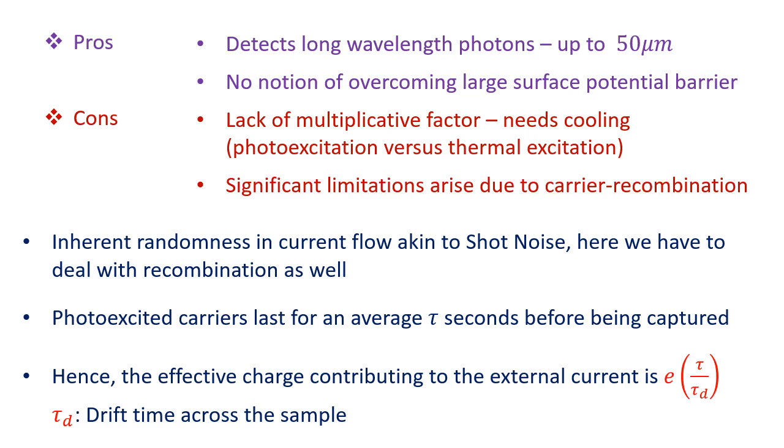Because they are of similar wavelengths and energies. So if we want to do a good job of this, one needs to cool these detectors so that the noise due to thermal photons does not overpower the signal which is coming from photoexcitation of infrared photons which are coming.